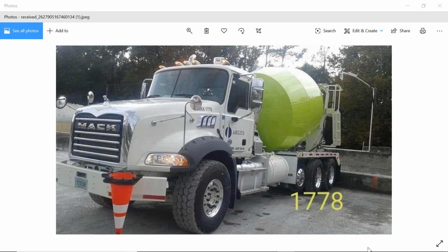1. Free moisture is equal to 2.81 minus 1.40, which is equal to 1.41%. 2. Free water is equal to free moisture divided by 100 plus 1, which is equal to 1.0141. Adjusted aggregate quantity